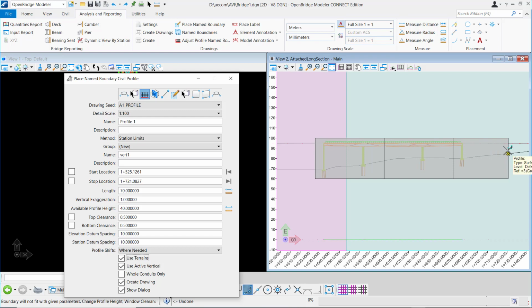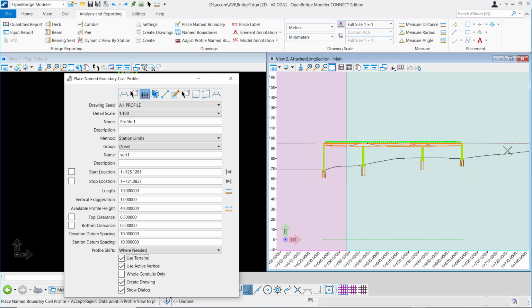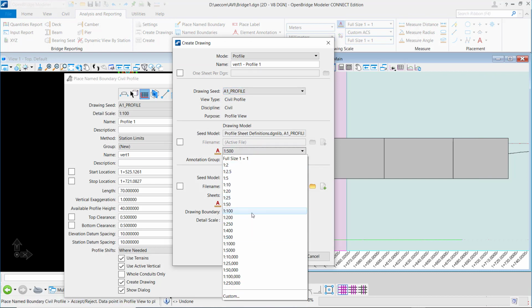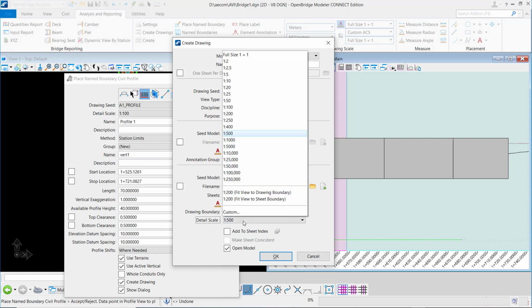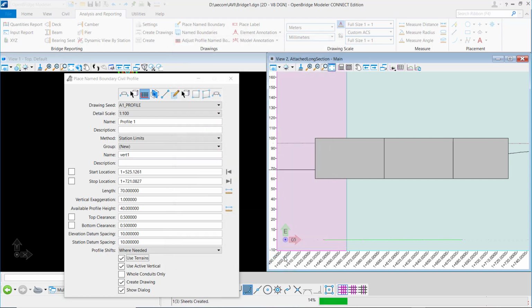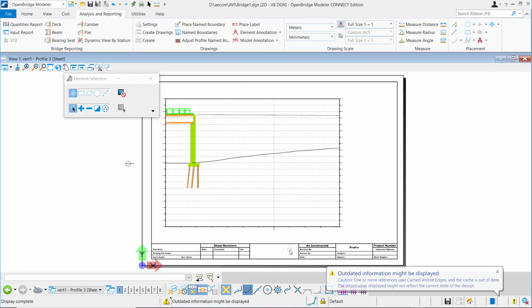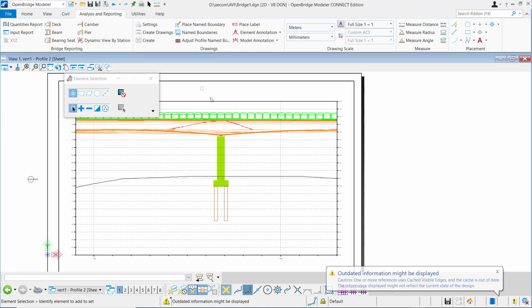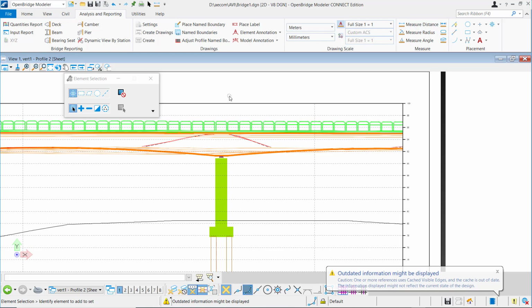And so we can define that we want 3 sheets covering the profile, defining what the base of our drawing is, what the scale of that profile is, and the scale of the dimension that we will put afterwards. And in the same way, the profile is automatically generated with a grid, so we can review these different drawings and add dimensions if needed.